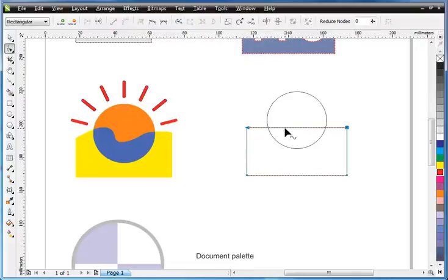Let's see if this worked. Try the top line. It's converted to curves. Now try the right line. As you can see, the line was also converted to curves. Well, it isn't that important for us, to tell the truth. I'm never using the reverse direction icon. I just draw a selection box over the nodes I want to select.